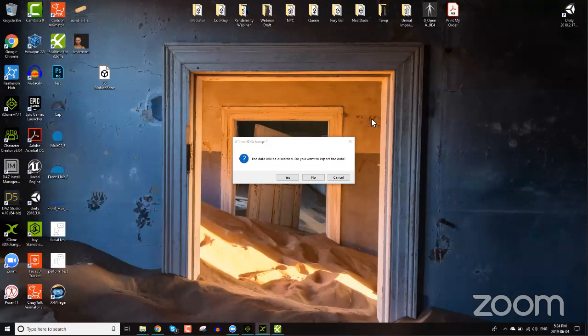Okay, question here from Sam. When I'm using FaceWare, occasionally, even if I'm centered, it kind of drops the features of the character I'm working on, so it kind of looks like their faces are melting. Is it something to do with my default settings? This happens often, Sam, and the only solution I find is to do a recalibration. Even sometimes just exiting real time for iClone and restarting it works in certain situations.